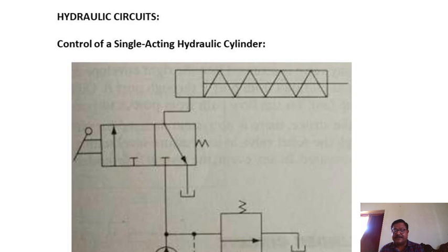Each of the above mentioned events and activities constitutes a cycle. The designer has to synchronize all these cycles into a single cycle. So he has to make a compact operation by including all operations. All operations means unloading of jobs, loading of jobs, and then clamping, declamping, forming operations. As in the example I gave in this session, the lathe operations: the clamping, declamping, unloading, loading, and then the machining operations are nothing but the forming operations.